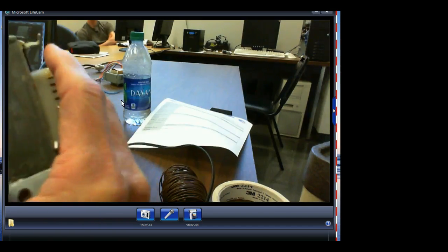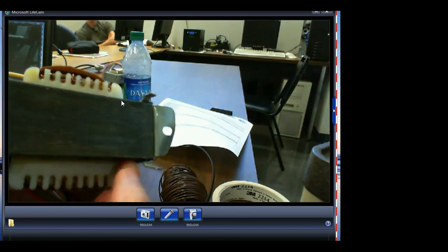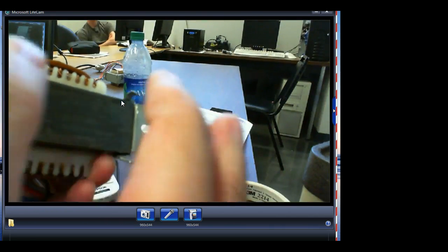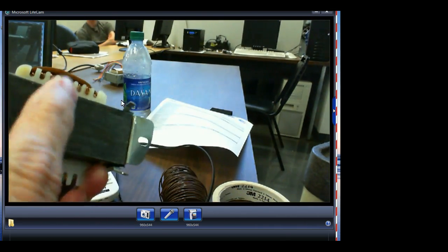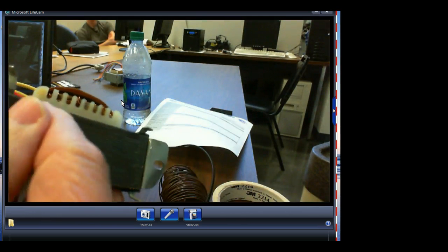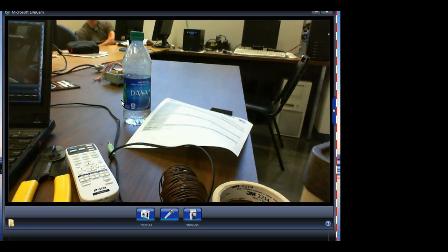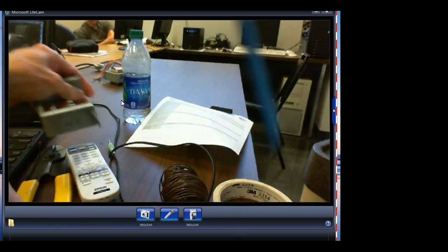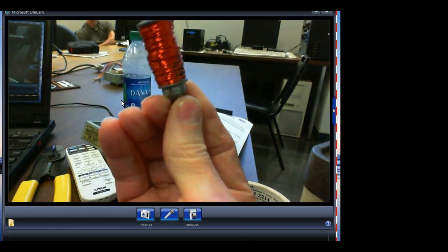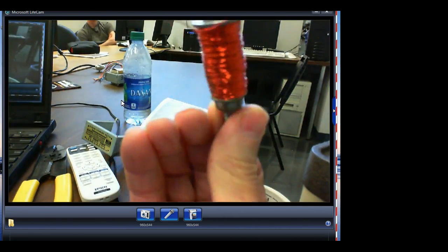You understand why? So what this does is now the core is not acting like a conductor of electricity. It's acting like a chunk of metal. So the magnetic fields can combine in each plate, but the currents can't, right? Does that make sense? So this is actually a transformer. So this right here would make a crummy transformer because it's got a solid iron core.